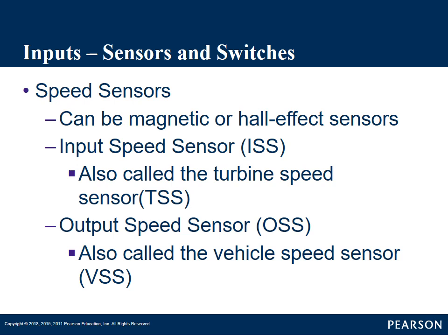So we can use this to determine how fast, and we can use our sensors on our engine to tell us the load, with our throttle position sensor probably being the most prominent sensor that they use to determine the load of the vehicle. That kind of takes the place of our throttle valve on just our hydraulically shifted transmissions. There are many uses for these sensors.